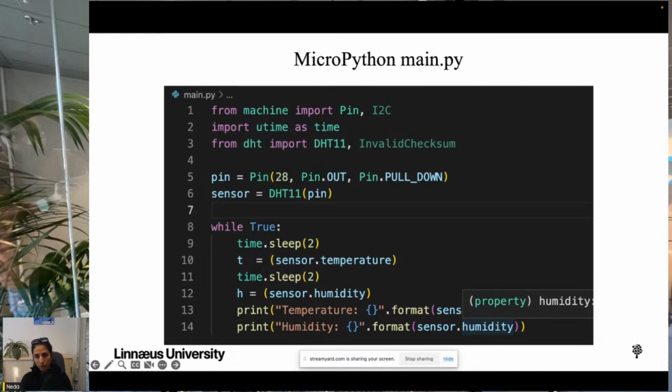But maybe someone asks, what does not being actively driven mean? I should say that actively driven refers to a situation where the voltage level on a pin is being controlled by a signal from the microcontroller.